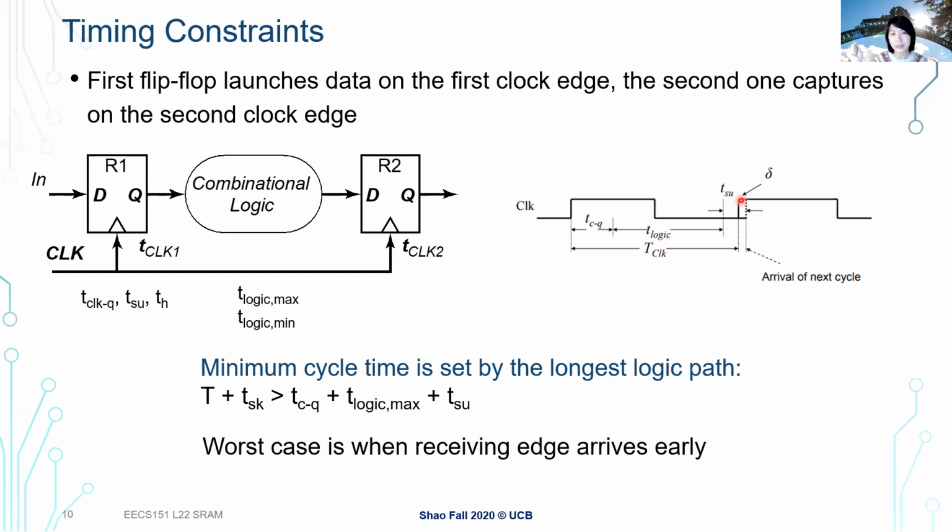So this is how thinking about the spatial relationship between my first clock and second clock sometimes helps our timing analysis, but sometimes it also hurts. So it really matters whether it is a positive skew or a negative skew.